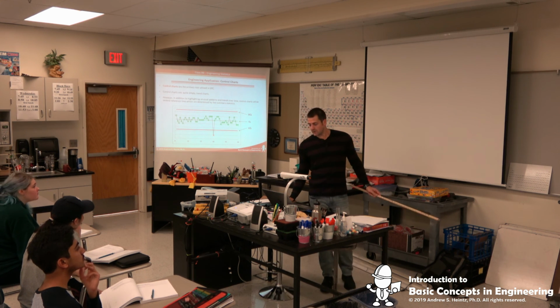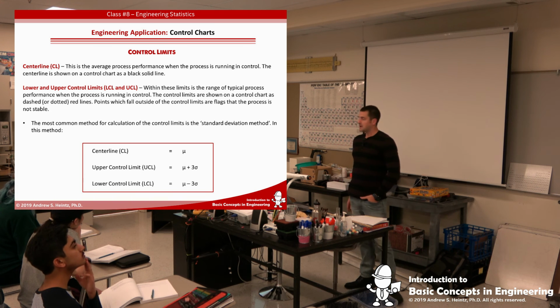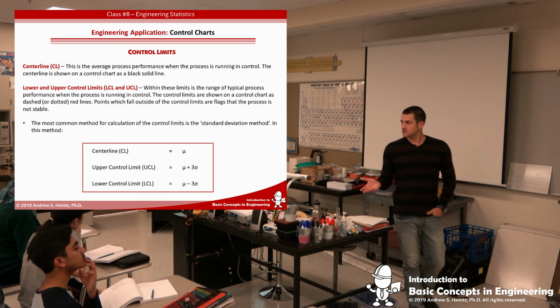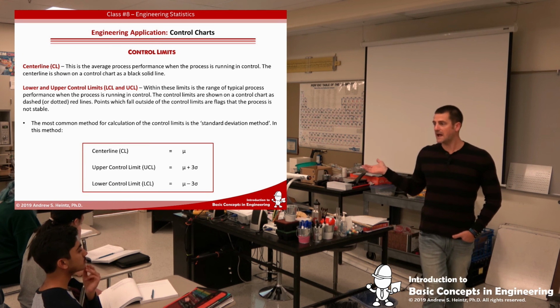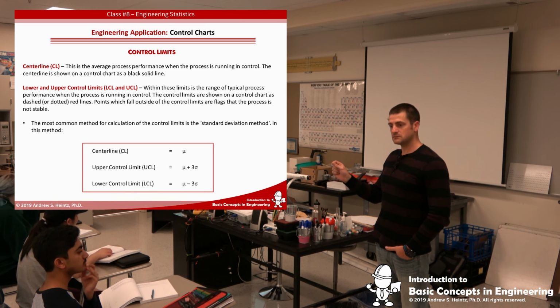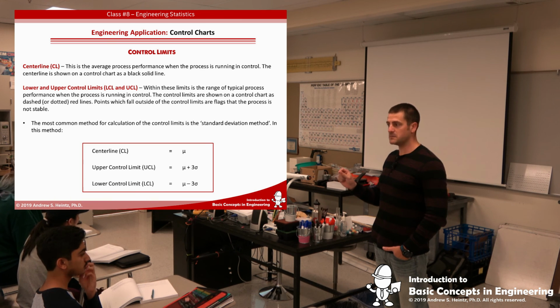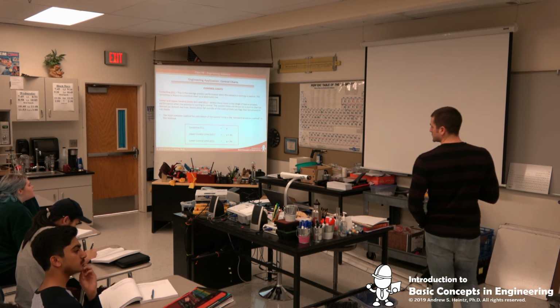So what we've done is, A, we've put control limits on the process. Now again, we talked about 6 sigma. We talked about our process. So our upper control limit, we're going to set at mean plus 3 standard deviations. And our lower control limit, we're going to set at mean minus 3 standard deviations. Right? Makes sense. It's just creating our normal distribution.